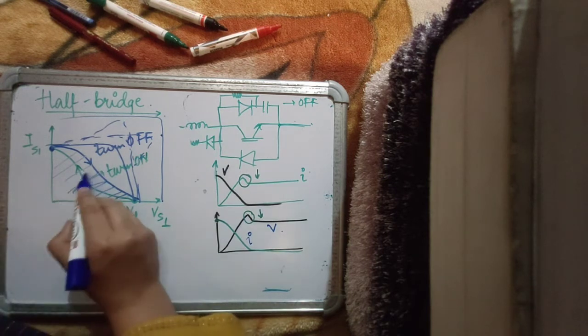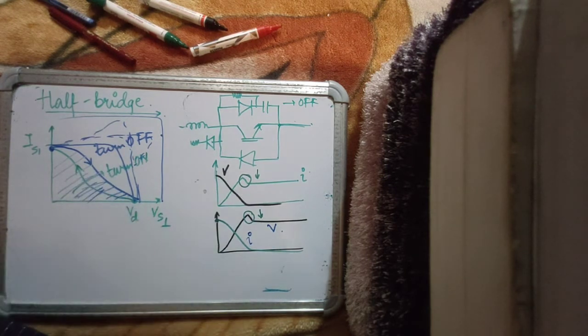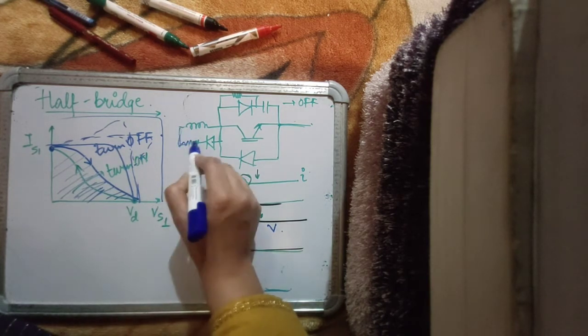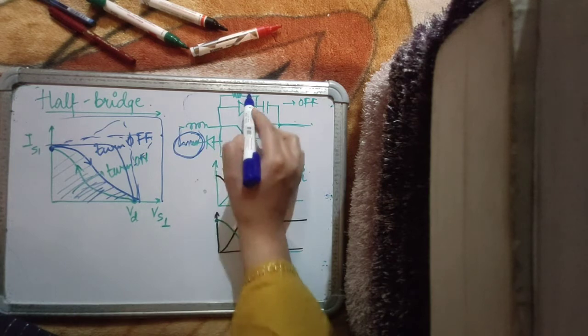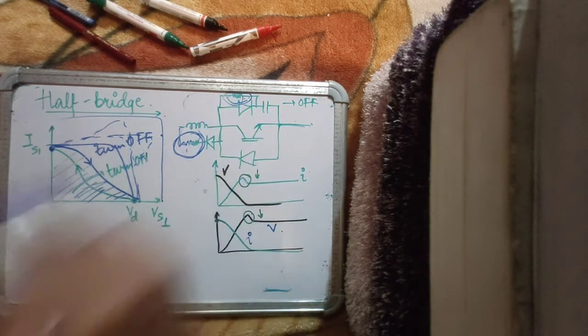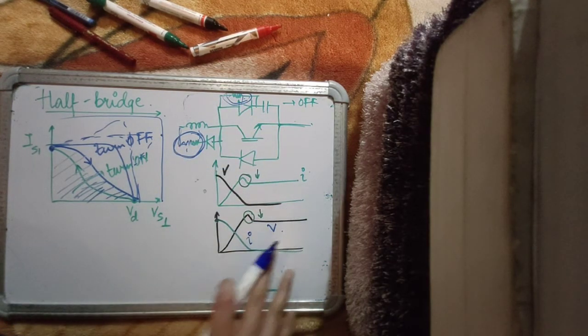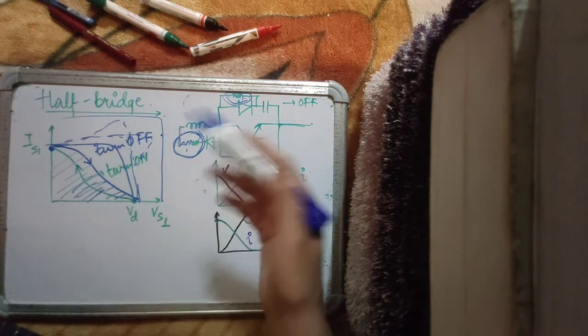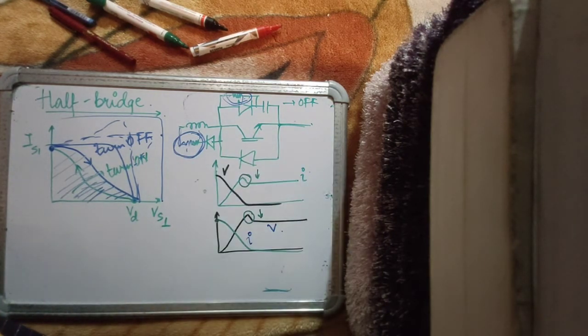But although you have reduced switching losses with snubber circuits, there is a lot of likelihood that you may have overall decreased the efficiency because there will be losses happening in these snubber resistances. So although the switching losses might be reduced, snubber losses might be incorporated into the circuit, which will overall not really help your efficiency much.